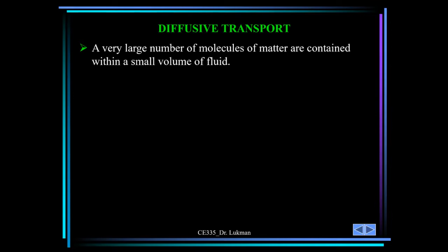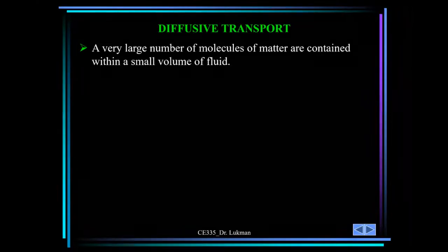And then we have dispersion, which is more realistic because it takes care of the spread caused by the variation in the velocity at different regimes. We looked at the dispersive flux as well as the advective flux.